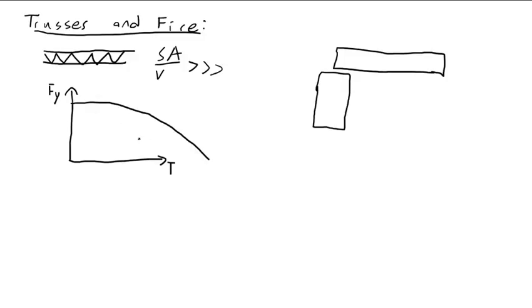Yes, it is true that in a normal fire you're not going to melt steel using even jet fuel unless you would need some sort of sealed container like a furnace for that. But you don't need to melt steel to cause a steel beam to fail because the yield stress, the stiffness of the material declines greatly as it heats up. Before, okay, you can think about this. Like imagine, I don't know if you've ever been to a Renaissance festival or even if you've just seen an old-timey movie where you see some old-timey blacksmith, right?